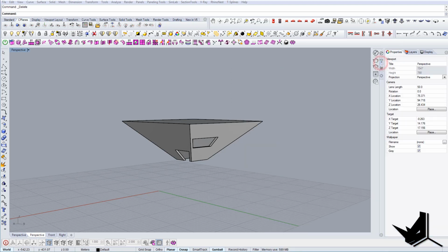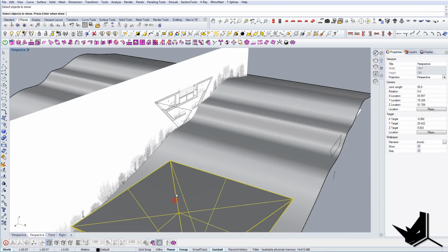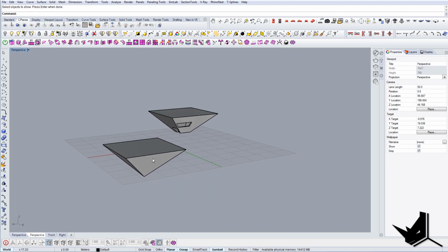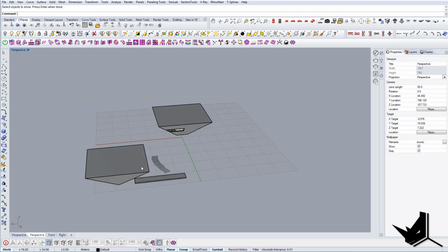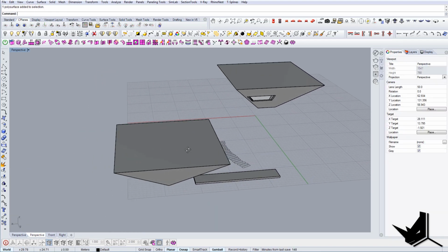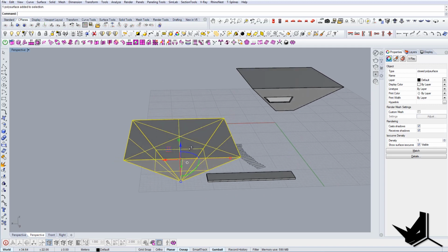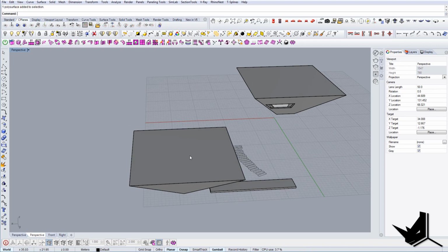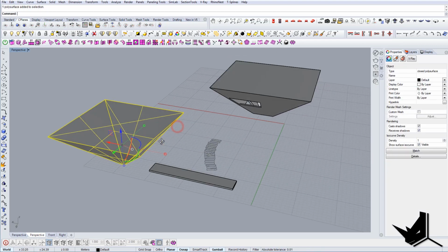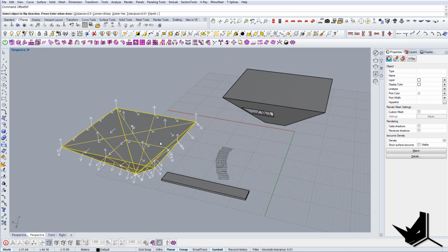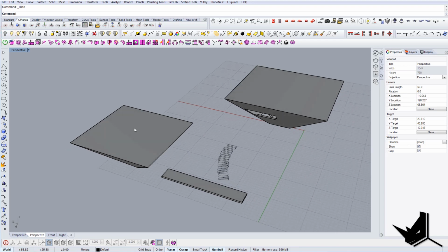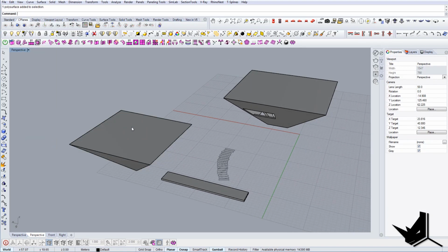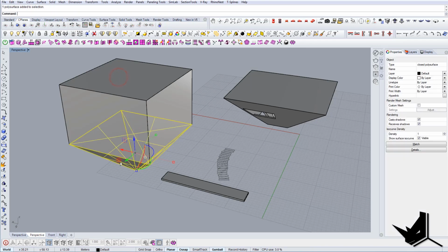for now. And now we have, of course, this area here, which will be the swimming pool, and we have basically the steps and the stairs there. So again, we can do the same kind of principle to create basically the swimming area there. So let's actually do the offset surface on this one as well. Offset surface inward 0.5. We can leave it to be the same. And here I'm going to extrude this surface upward, and let's Boolean union these guys.